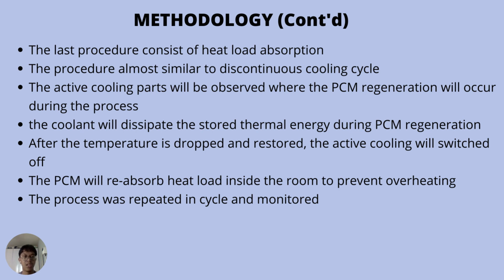So basically, the other parts, the circulating pump and also the cooling source, will be off, while the heat loads will be the ones that switch on during this process, and it will trigger the phase change material to regenerate, where the coolant will dissipate the stored thermal energy during this regeneration.